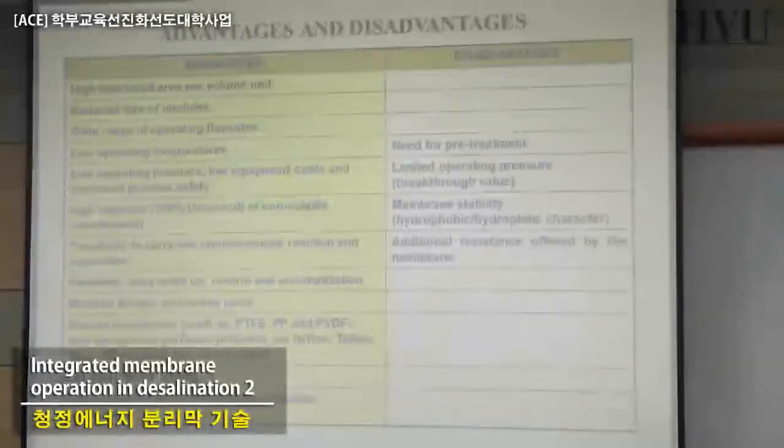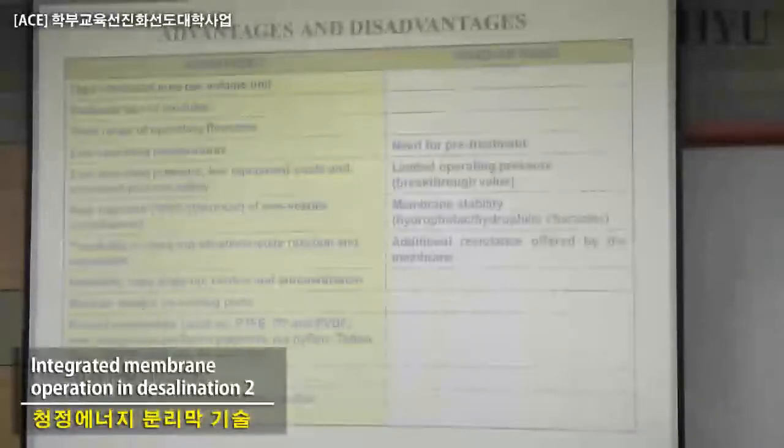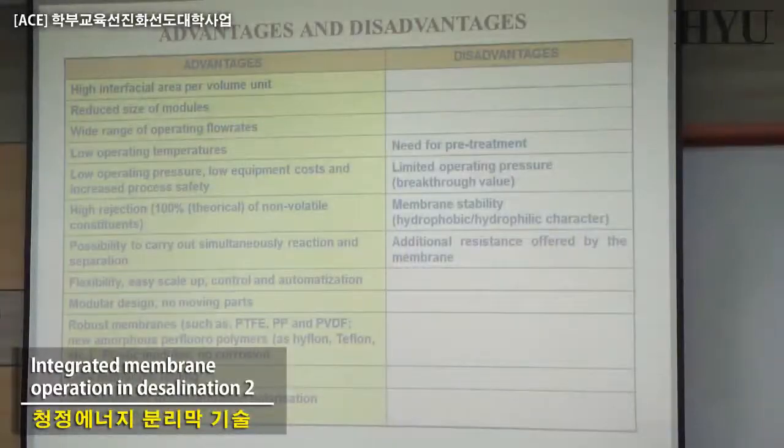But it rejects following some equation that we will see, the Laplace equation, telling you that if the pressure increases too much, the liquid can penetrate into the porous system. So surface energy is not strong enough to avoid this. This is called LEP, liquid entry pressure, and we have to be sure that you never apply a pressure in your system higher than the LEP.